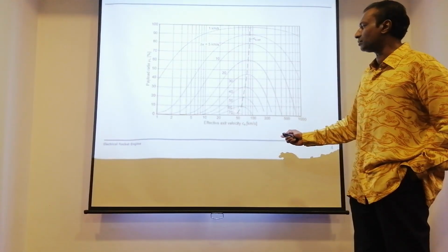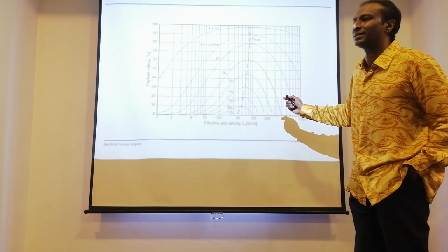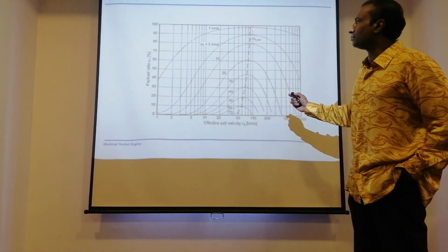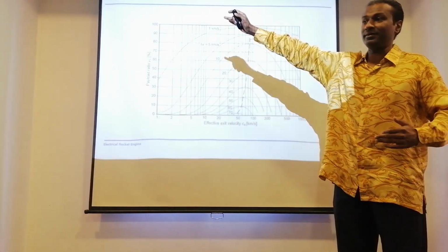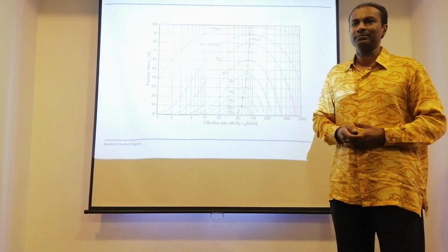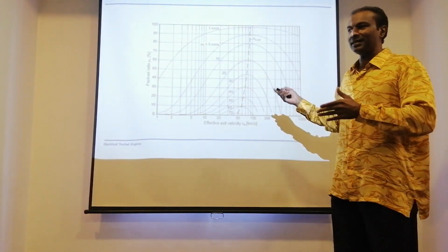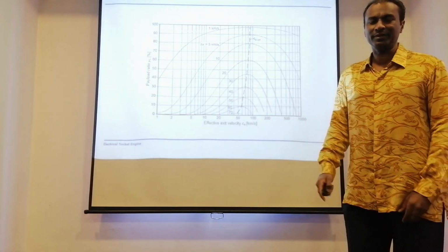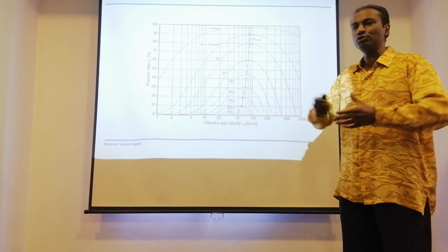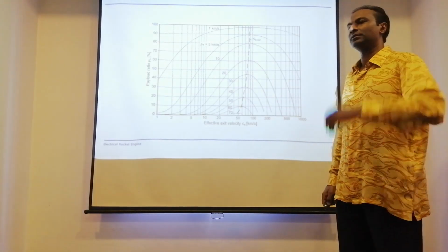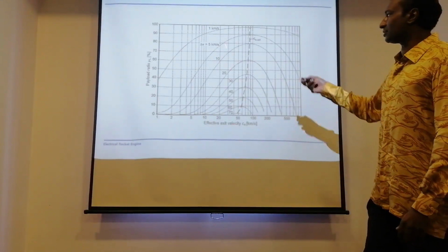But assume your delta V is small, and you don't need so much delta V. Your payload ratio will be quite high. That means if you want to fly very far, you can't send big things. If you want to fly a very short distance, with the current technology, you can send a very big thing. If you want to send a huge payload with this technology, you can reach only up to a certain level, maybe up to here. So it reduces accordingly.